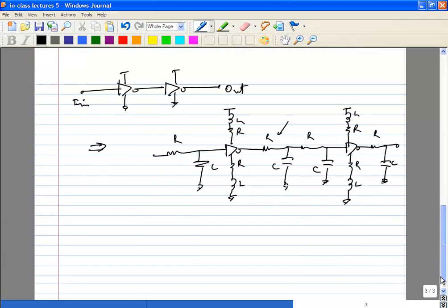Okay, and obviously this is a very important step, because LPE is typically where you will find out issues with your layout. So design the circuit, layout, LPE, simulate, and then you will see degradation. You will go back, modify the layout, so you can find out where the layout gets spoiled, where the design is most sensitive to layout.